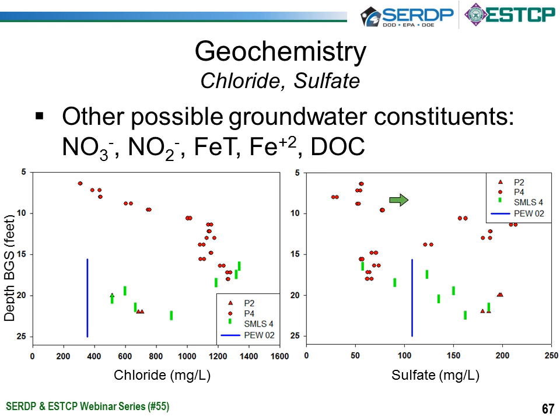For sulfate, again, very dramatic increases and decreases in concentration, good correlation between the passive profiler and the well data, and again, if you were using more traditional well screen intervals, you would not be able to see this drastic decrease. Given that the chloride is probably due to some type of seawater intrusion, this rapid decrease before chloride decreases is probably related to sulfate reduction, so that wouldn't have been picked up. So basically, it gives the ability to look at very fine resolution geochemical conditions that could change over very small intervals.